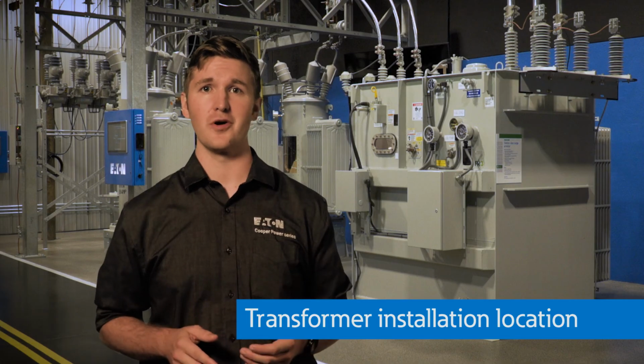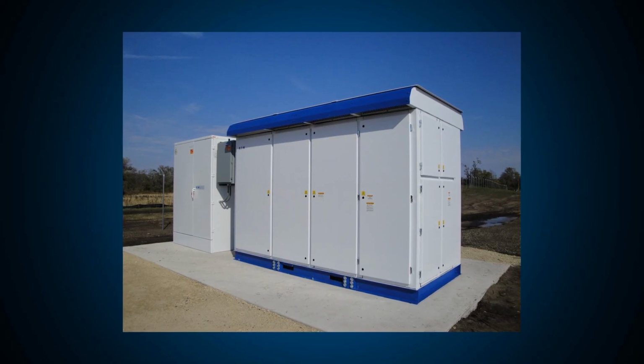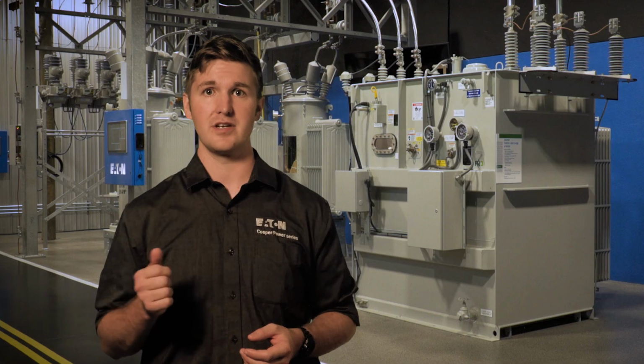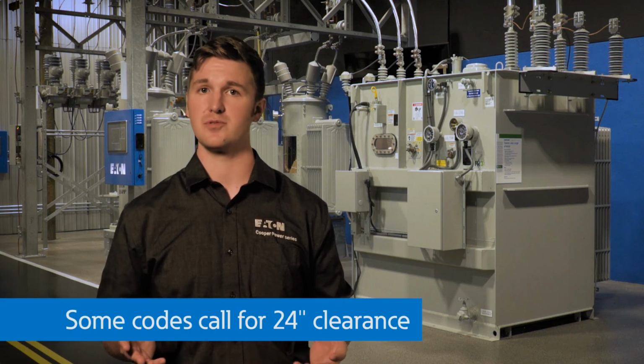A transformer should be located on a level concrete pad of sufficient strength to support the weight of the unit. The location of the transformer, whether indoor or outdoor, should provide for adequate accessibility, ventilation, and ease of inspection. Generally speaking, the transformer should be at least 24 inches from any obstruction.